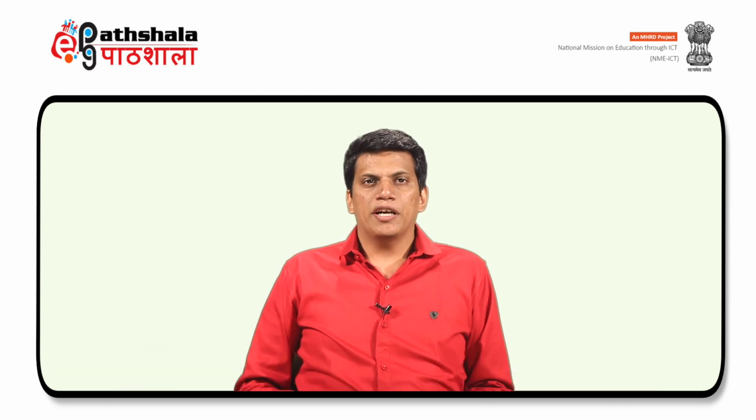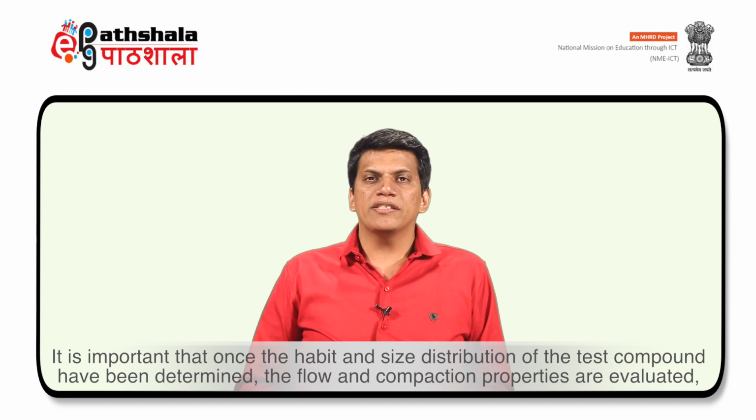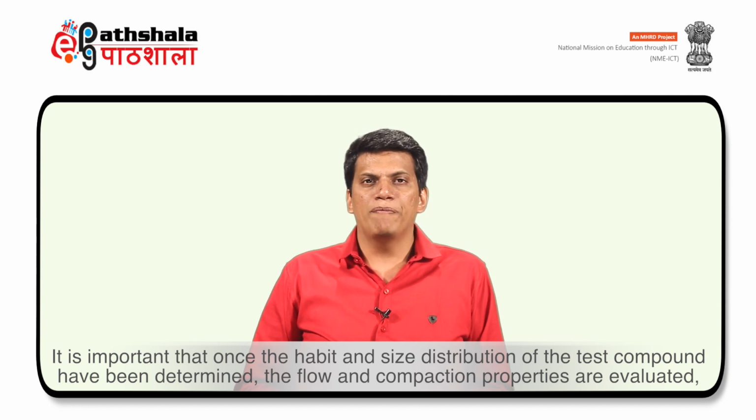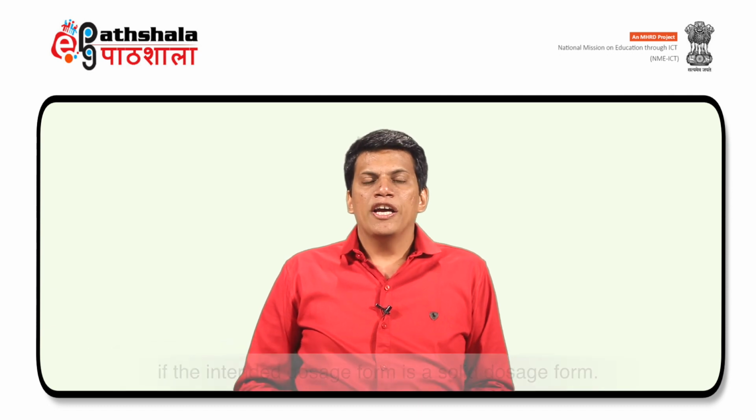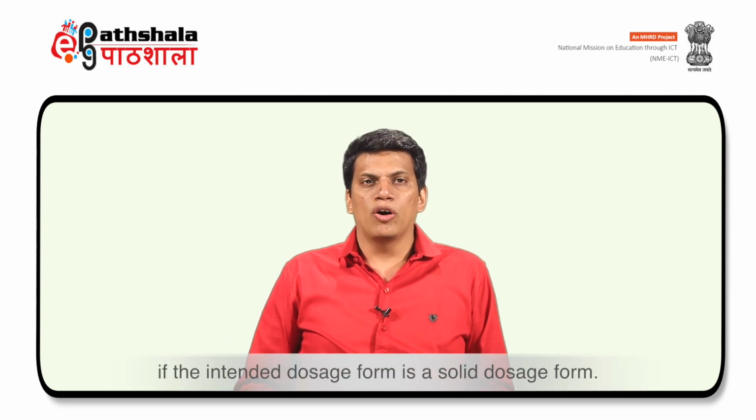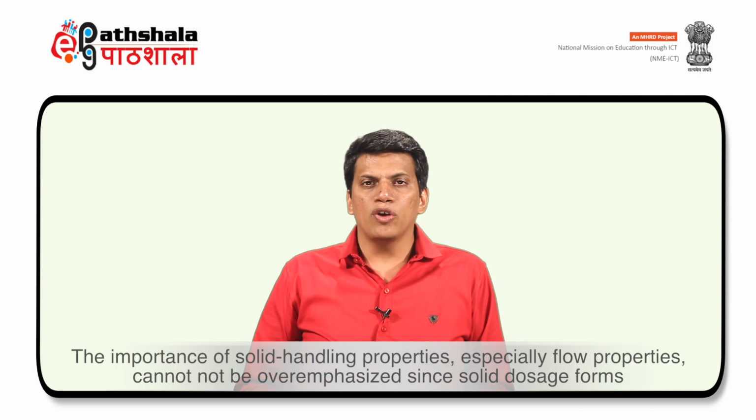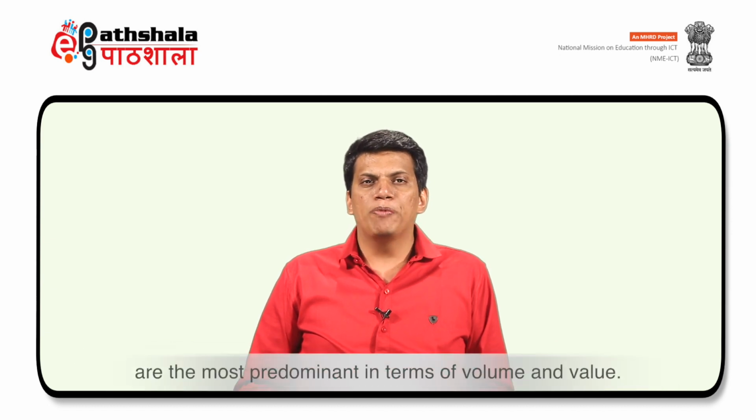process to use. It is important that once the habit and size distribution of the test compound have been determined, the flow and compaction properties are evaluated if the intended dosage form is a solid dosage form. The importance of solid handling properties, especially flow properties, cannot be overemphasized since solid dosage forms are the most predominant in terms of volume and value.